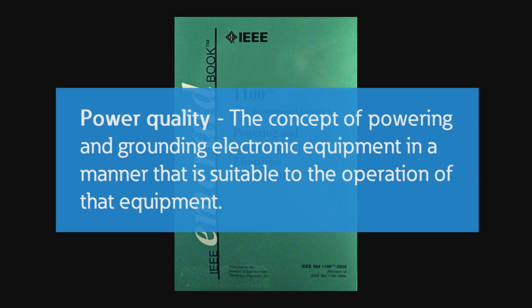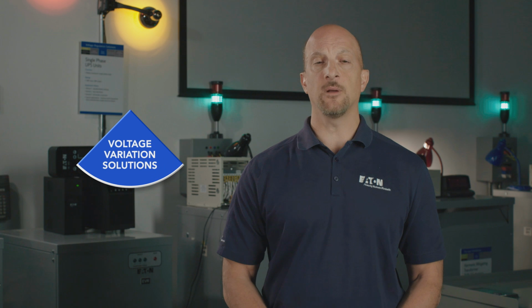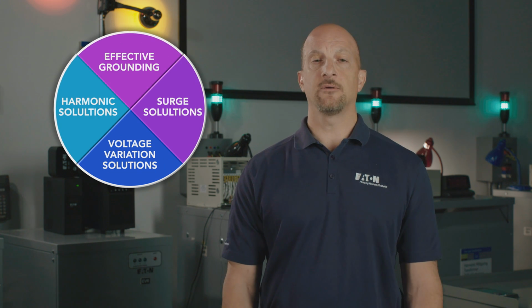Power quality is defined by the IEEE as the concept of powering and grounding electronic equipment in a manner that's suitable to the operation of that equipment. Basically, that means what works for you and your equipment. Every system and many loads are different and respond differently to PQ issues, but power quality issues can be simplified by dividing them into four main categories: voltage variations like sags or interruptions, transients or surges, harmonics, and grounding.